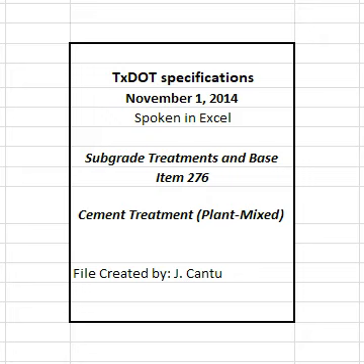4.2 Placing. Place the cement-treated base on a subgrade or base prepared in accordance with details shown on the plans. Bring the prepared roadway to the moisture content directed. Haul cement-treated base to the roadway in clean trucks and begin placement immediately. Place cement-treated base only on an area where compacting and finishing can be completed during the same working day. Spread and shape in a uniform layer with an approved spreader.